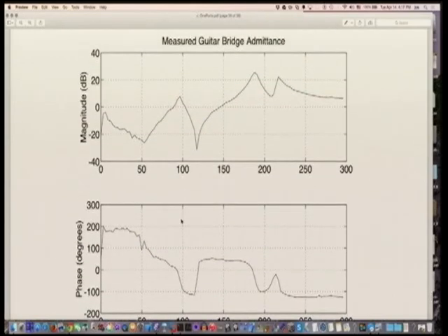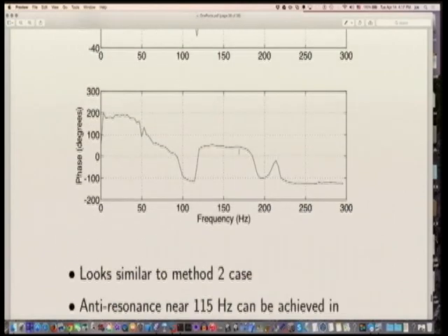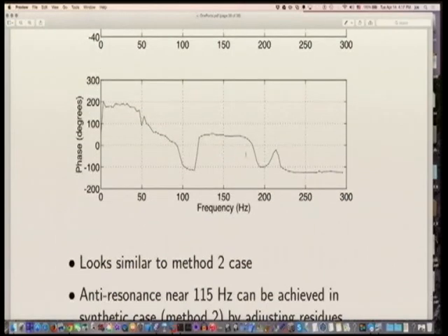So that's our measured admittance. And then here is its phase. And remember, this has to be between plus and minus 90 degrees. So this is a nice check on your experimental apparatus. Now, sure enough, the low frequencies are not obeying the positive real constraint. So we don't know what's going on down there, but we don't care, so we're going to filter it away.